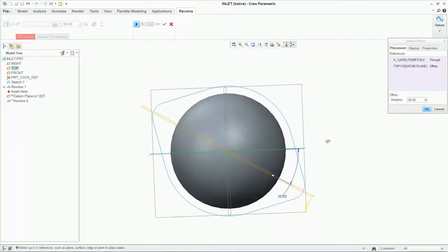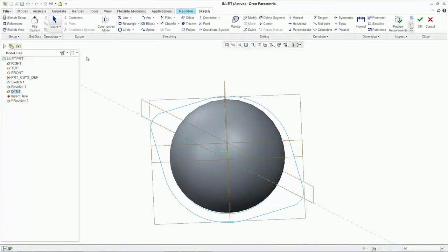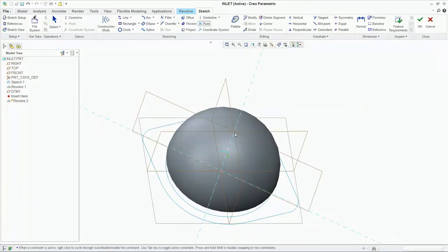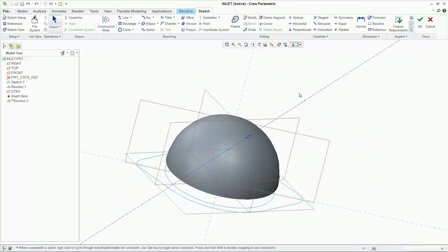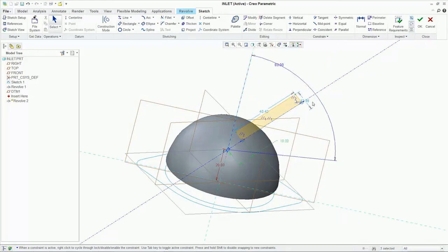Again, by defining the center line and axis of rotation, a simple rectangular sketch will result in the desired 3D geometry. From this rough sketch, we can manipulate the dimensions to fit specifications. The attached preview gives you a fully generated feature preview before you commit to finalizing the feature. This gives users full confidence that the feature they are creating will work exactly as they see it on the screen when they hit the middle mouse button or OK.